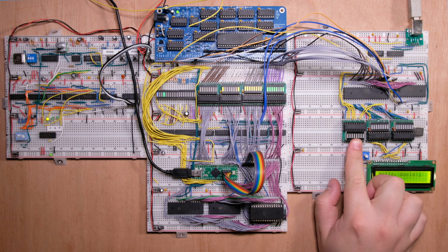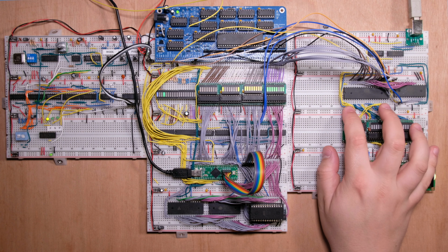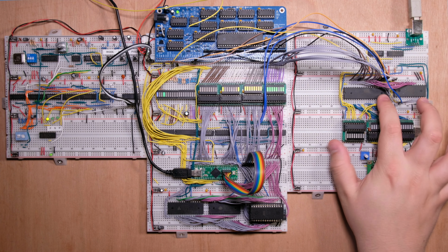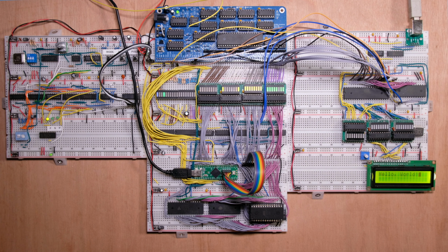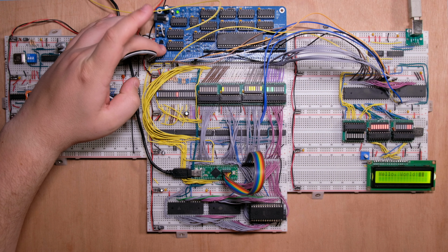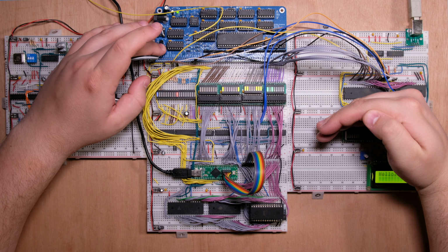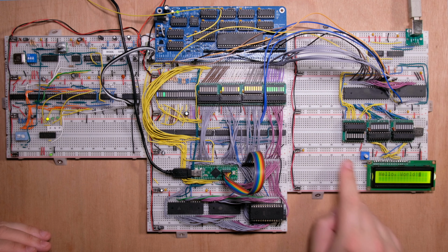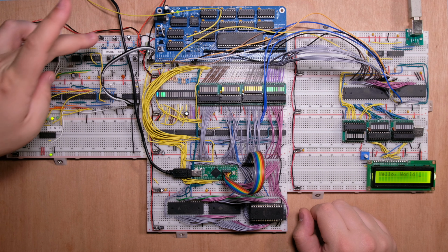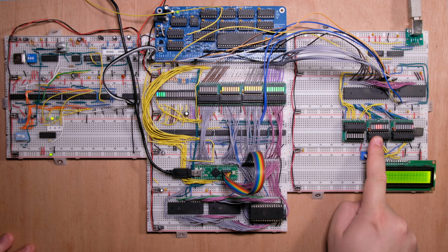All right, so I've added a new 8-bit LED here. So the LEDs on the right are for CA1 to CB2 on the VIA, and then the LEDs on the left are for the status of the serial link. And you can see if I reset, not sure how well you can see that on camera, the transmit LED turn on here when the string is transmitted. And if I switch to the slow clock and reset, you can see the computer talking to the LCD over the VIA.